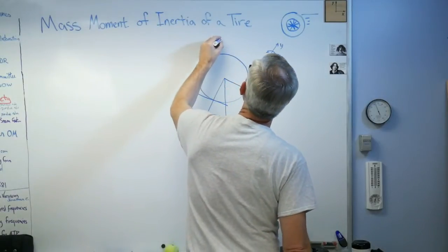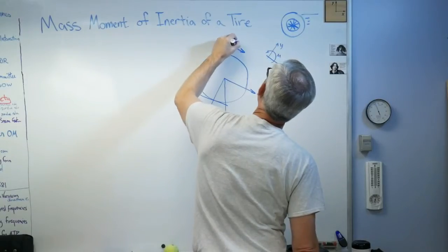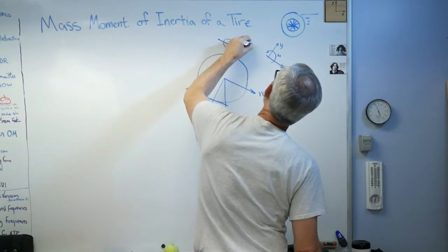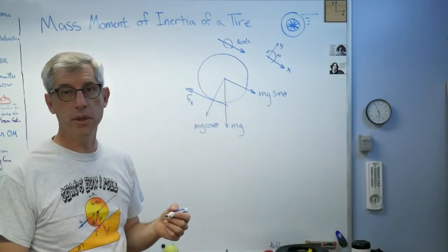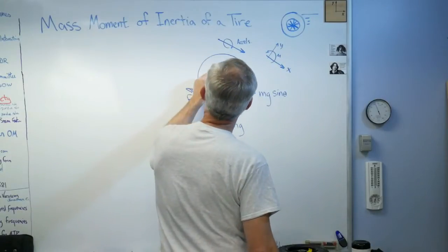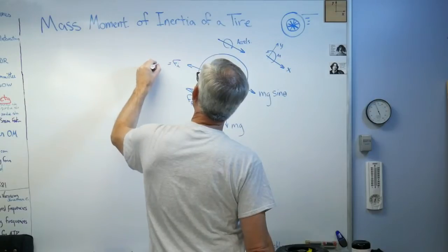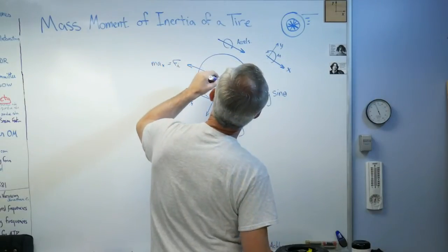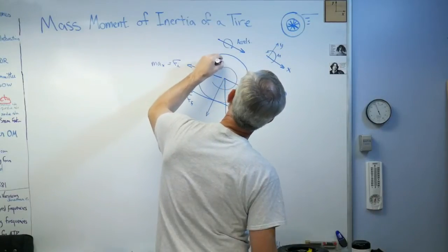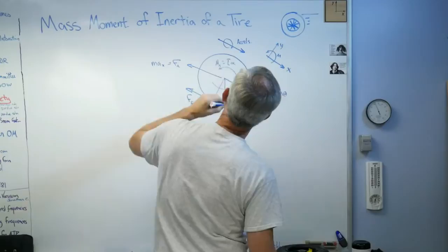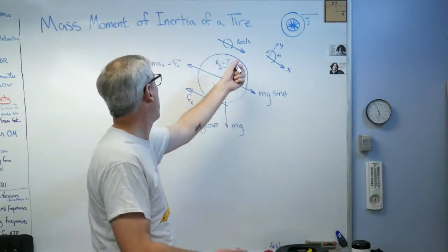So we need to know where the accelerations go. The acceleration goes there and there. Okay, those are the accelerations, right? And the inertial forces and the inertial moment act in the opposite direction of the acceleration. So that's the inertial force, and that's m a_x in the x direction, and this is the inertial acceleration, m inertial, and that's I alpha.